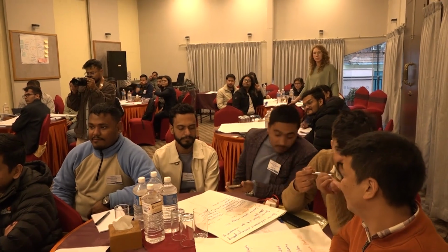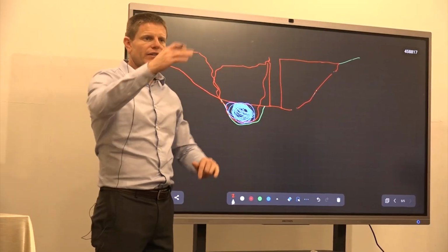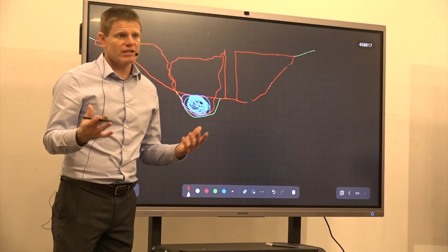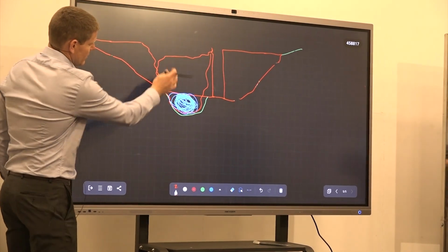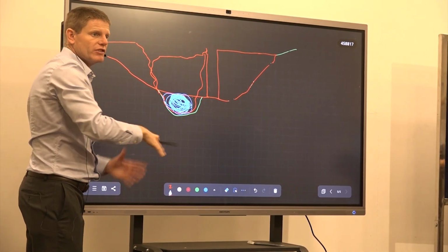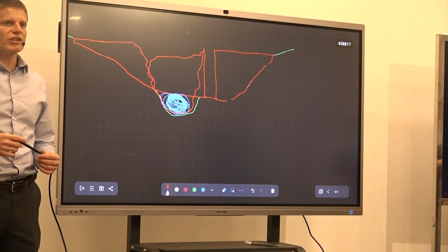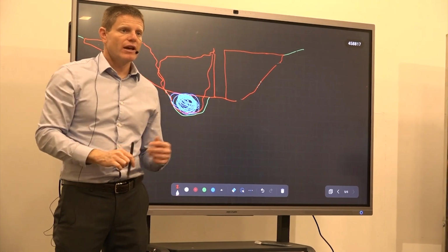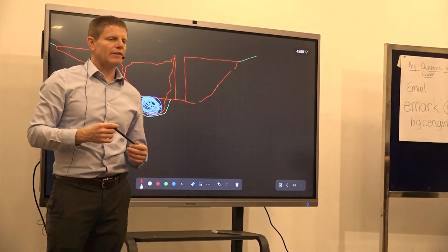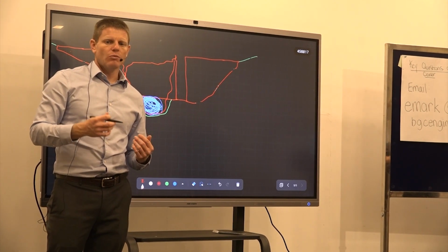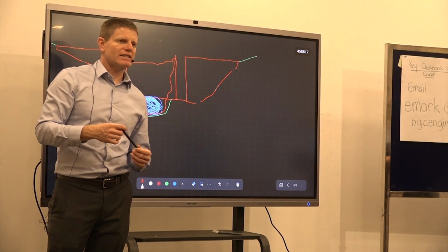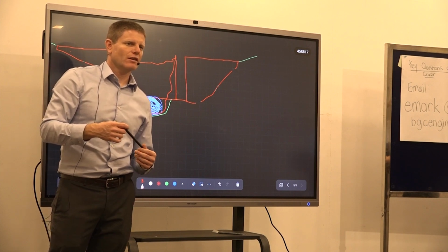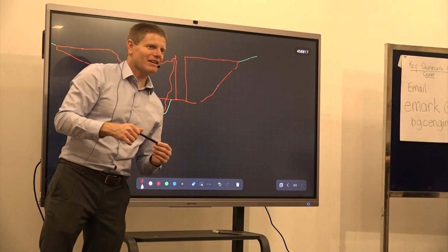Okay, that's a good point. That's a great point. So I've assumed that you don't have any weakness in the bedrock, but I think the point you're making is that potentially the bedrock is not strong. It could be very weak, and if it's weak, that could make this type of failure more possible, because then you don't get the bridging effect from the concrete that was mentioned, right? So again, it doesn't have to be that there's an answer to this, but you're listing the factors. And so if you decided, well, maybe that's true, maybe the bedrock is not strong enough, what would be a next step that you could take to try to investigate that question? I'm putting you on the spot.